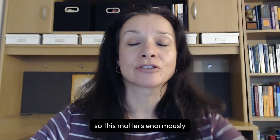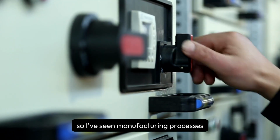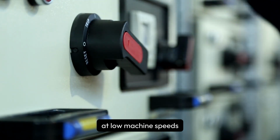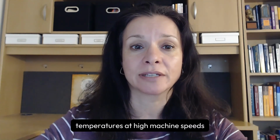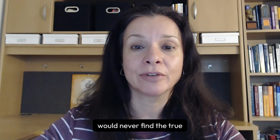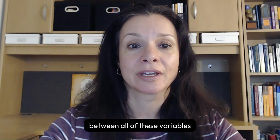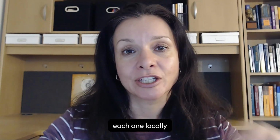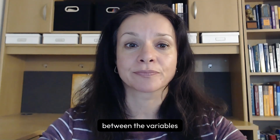So this matters enormously when working with multiple variables. I've seen manufacturing processes where the optimal temperatures at low machine speeds were completely different from the optimal temperatures at high machine speeds. So an engineer that only changes one variable at a time would never find the true optimum between all of these variables. They would optimize each one locally and miss the actual global relationship between the variables.